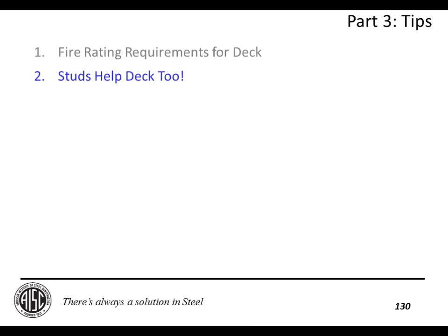Number 2, studs help deck. Normally the properties given in the deck manual for the allowable applied load onto a composite deck are based on shear bond tests. So actual testing that pushes the slab until there's a break in the bond between the embossments and the concrete. All composite action is trying to prevent two surfaces from slipping, right?